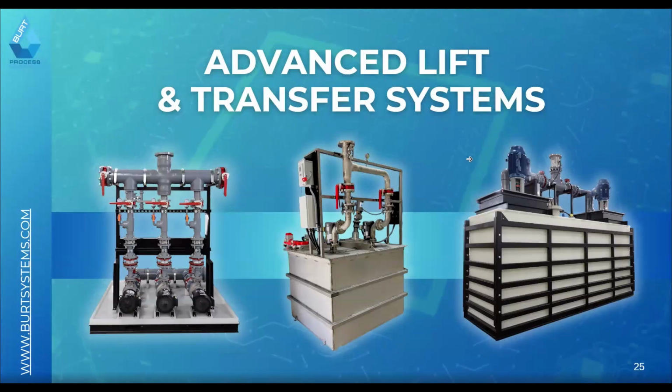Yep, and the correct answer is all of the above. Well done, everyone. So basically all of those things help contribute to why you would use a duplex pump system. Having the option to use one or the other helps to even out the pump wear and to increase the pump life because you're using them less often. As well, if you have any volume spikes coming into the system, being able to use both pumps simultaneously will help to handle that additional volume.